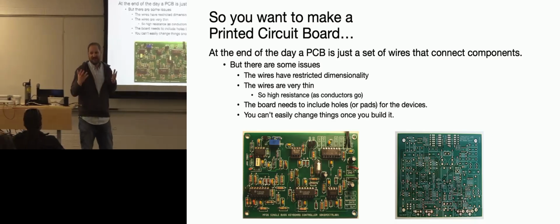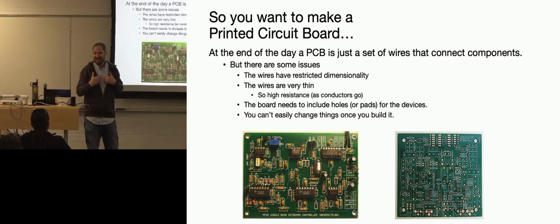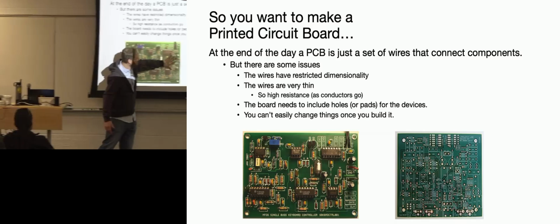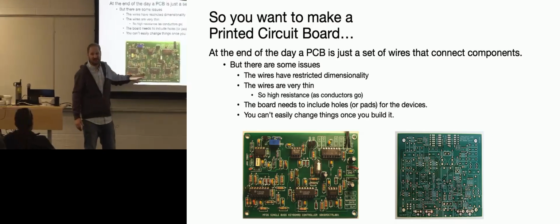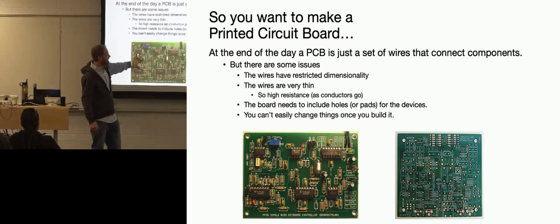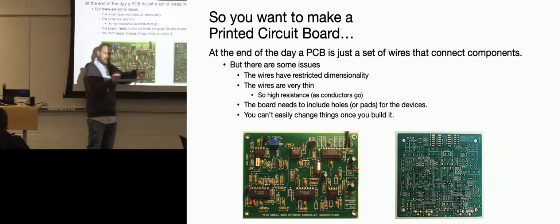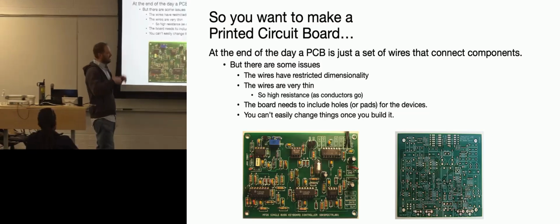And my brain says, that's a disaster. If I did that, I'd have solder everywhere, and it would be a big mess. But if you do it properly, that's the way you can solder everything from the bottom in one pass. And so that's why these are so cheap. You don't even have to put them in an oven. Now they have these little tracks, and the whole thing will be immersed on the bottom and get soldered in one go.